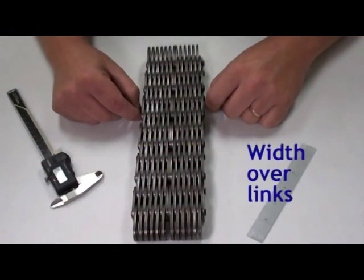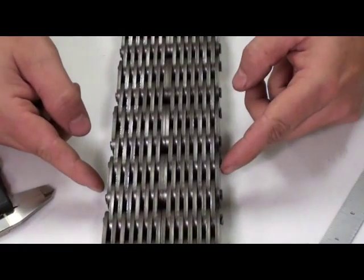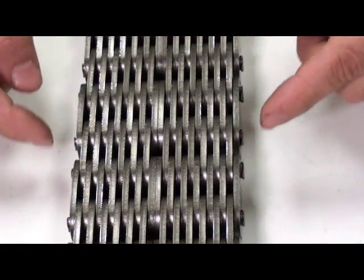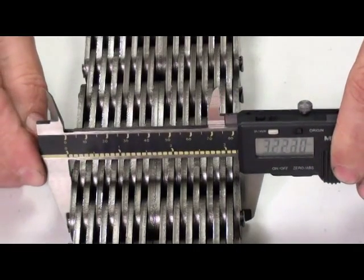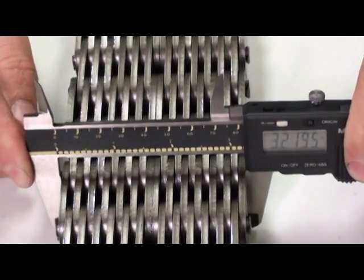The width over links is the measurement across the outside edges of the links at the chain's widest point. With the chain laying on a flat surface, measure the distance across the links. In this sample, the width over links is 3.22 inches.